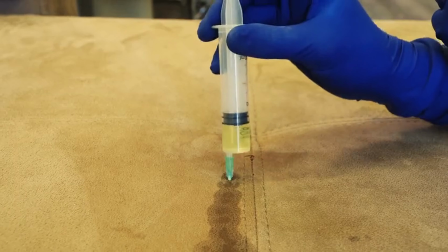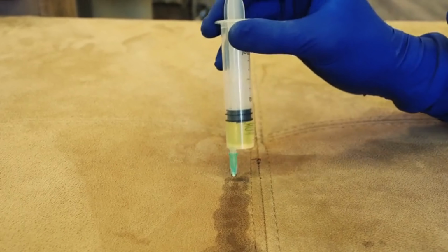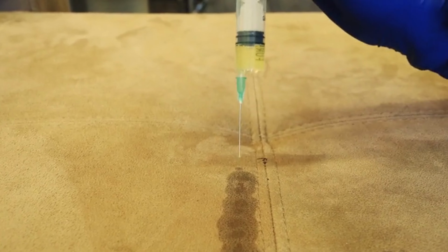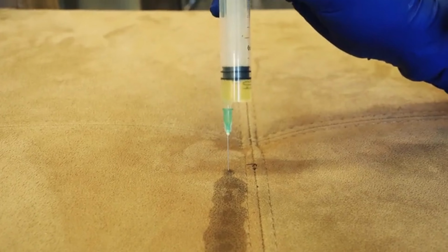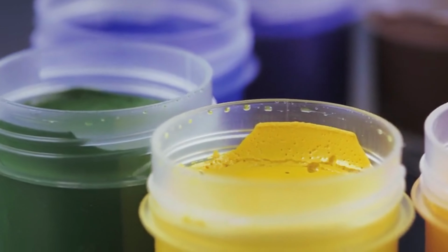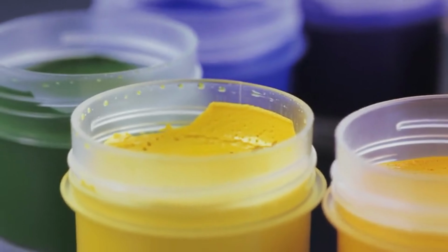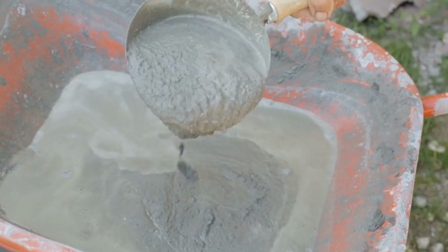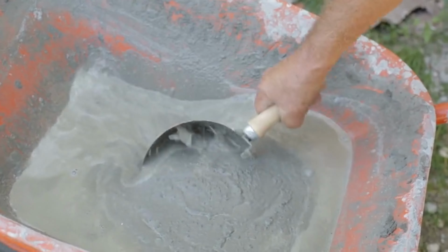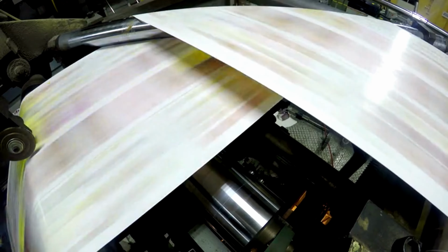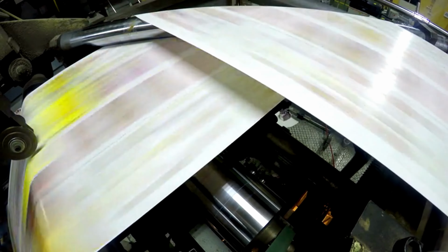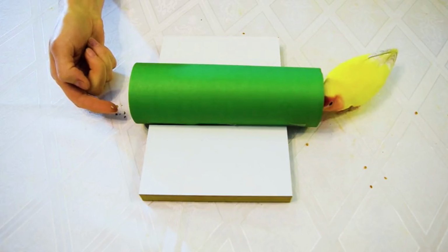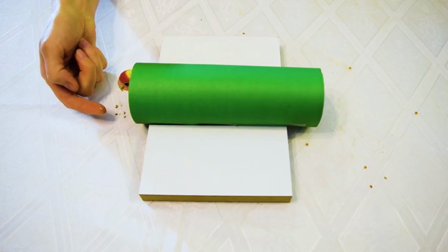6. Surface treatment and finishing. Once dry, the paper undergoes additional treatments. A. Sizing, water resistance. Additives like starch or synthetic resins are applied to improve printability. B. Coating, smoothness and gloss. Clay, calcium carbonate, or synthetic polymers are applied. Coatings affect paper brightness, gloss, and ink absorption. C. Calendaring, smoothing. The paper is pressed between polished rollers for a smooth finish.